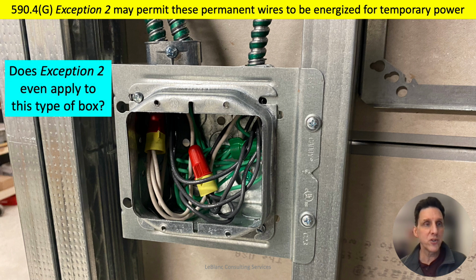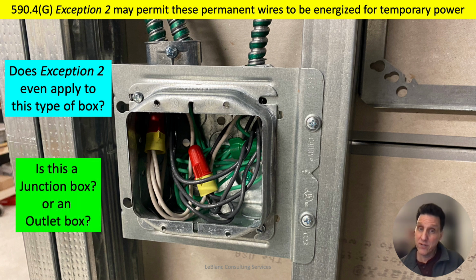One of them is, does exception 2 even apply to this type of box? Now, I don't know about you, but I would not call that a junction box. I would call that an outlet box. Now, exception 2 does say junction box. It doesn't say outlet box. So we could debate that, right? Is this a junction box or is it an outlet box? Some people might say it's a junction box. Some people might say it's an outlet box. I'm going to say it's an outlet box. But I still think exception 2, the intent is to apply to even this type of box, even though it says junction box versus outlet box.